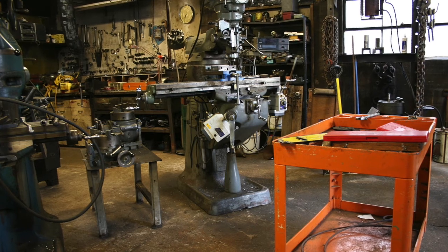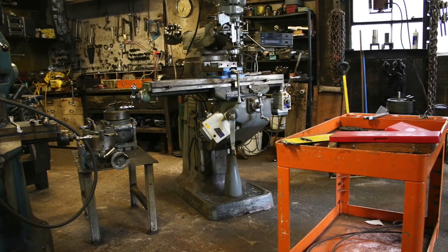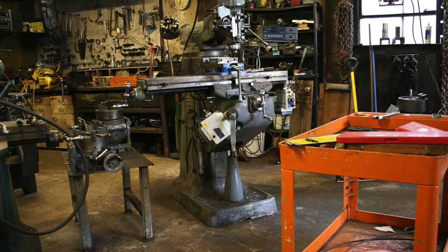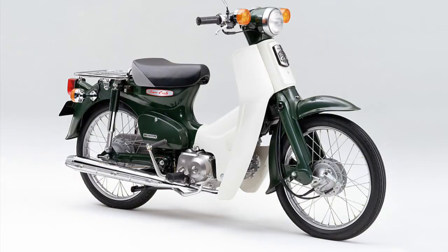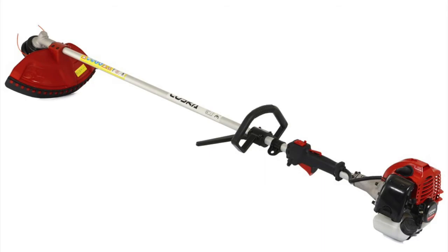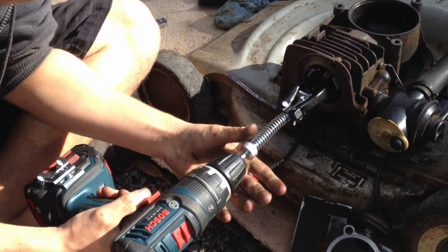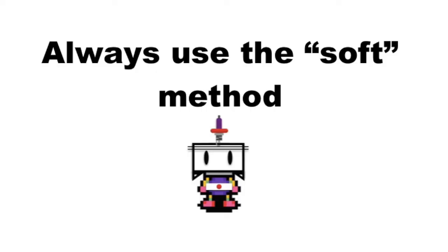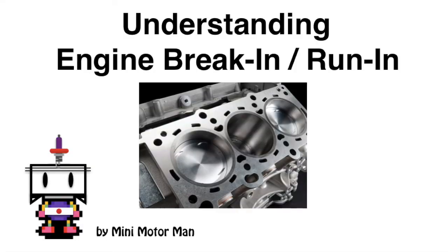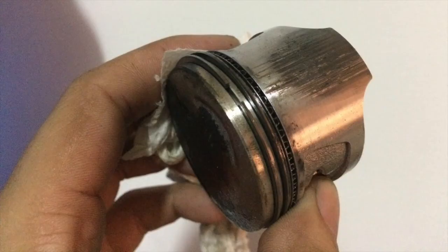So in the case of having your engine machined at a machine shop where you're unsure of the methods they're using to finish the cylinders, or in the case of very simple machines like cheap motorcycle engines or petrol strimmers, where a simple that'll-do finish is the most cost-effective way of doing something, then the soft braking method should be used at all times, as you won't know if your engine will overcook itself at high loads until it lets go, obviously, or in this case, seize up, and yes, I have done that before.